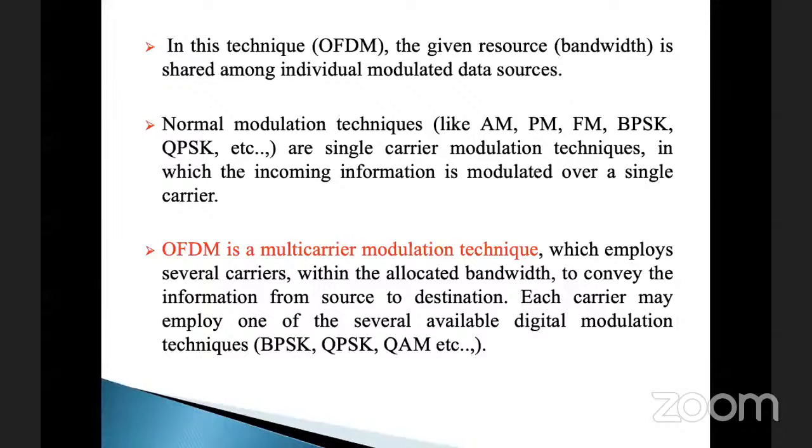But as I said earlier, when we want to improve the data rate, we have to send signals at a faster rate, with a lower symbol time, maybe 1 nanosecond, 1 microsecond. Then a lot of other pulses join into the communication channel because of multipath communication. There is always a severe intersymbol interference.